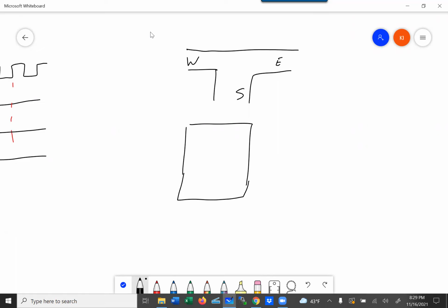So I'm going to rename it. You had the car presence when you built these modules, and I'm going to draw it as a system diagram that shows the module. You're going to have a car east come in, you had car south come in, and you had car west come in. And you said 0 means no car, and 1 means car is present, for the input.